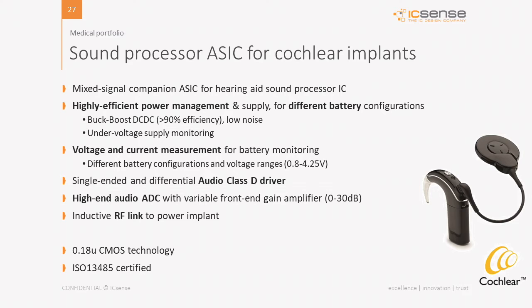So this mixed signal ASIC contains the power management for different battery configurations. Multiple battery configurations can be used within this product, where we have developed a flexible buck boost DC-DC converter and have also included some power monitoring. Also, voltage and current measurements have been done for the battery monitoring, and also a Class D and a high-end audio ADC is implemented on the chip.